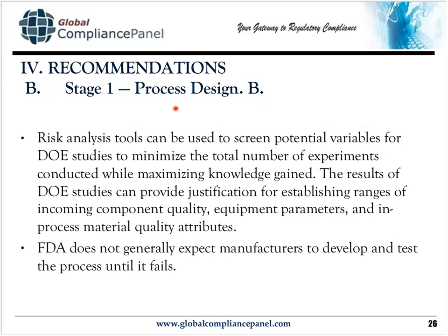Process design, again, you need to do risk analysis. If you're going to do risk analysis, a lot of times you'll end up with these arguments about, well, this element is important, this one is not, and somebody at a meeting insists that something is not, while somebody insists that it is, etc., etc. Well, design of experiment studies will allow you to look at these parameters and decide which ones really are important and which ones are not.